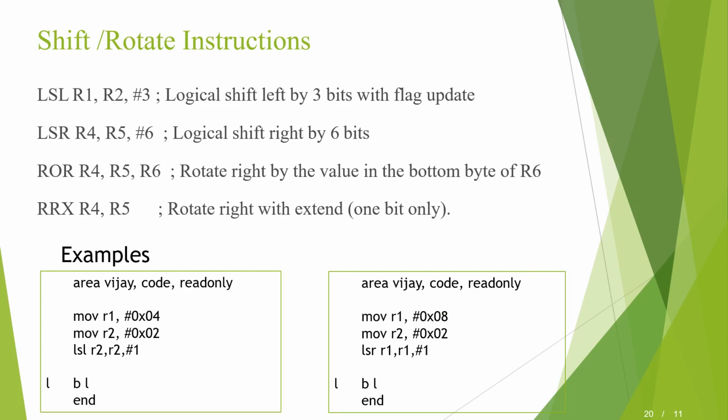And next one is shift and rotate instructions. Left shift and right shift, left rotation, right rotation. So you can see the examples here. When you use left shift or rotate operations, the barrel shifter will come into the picture.